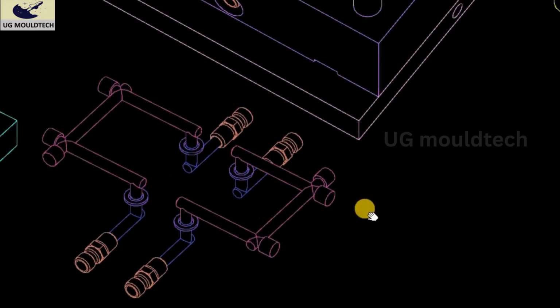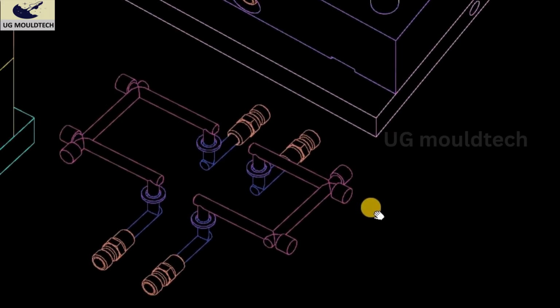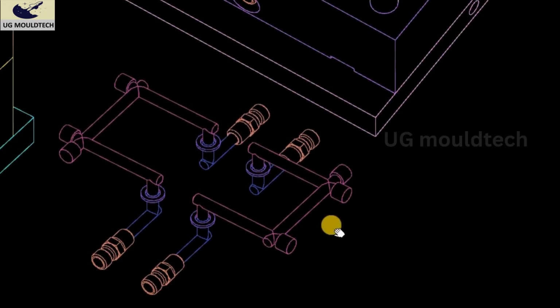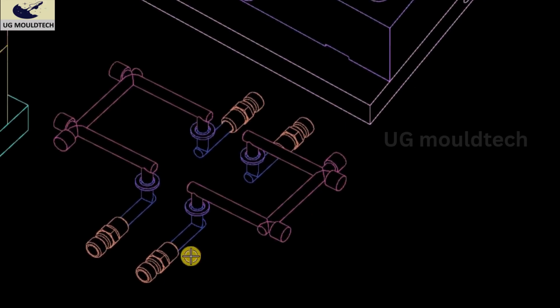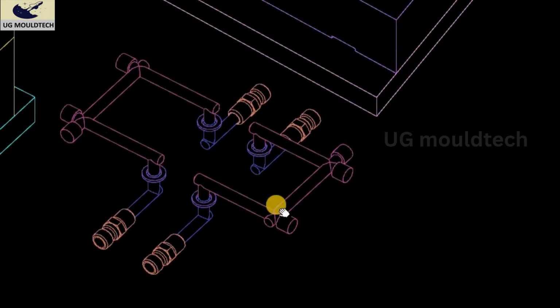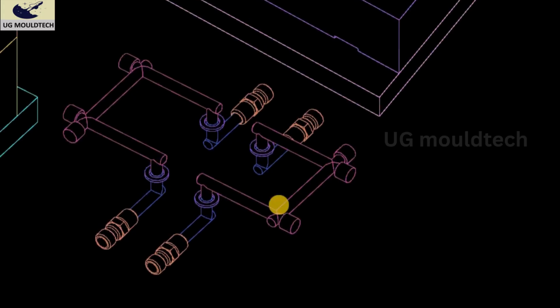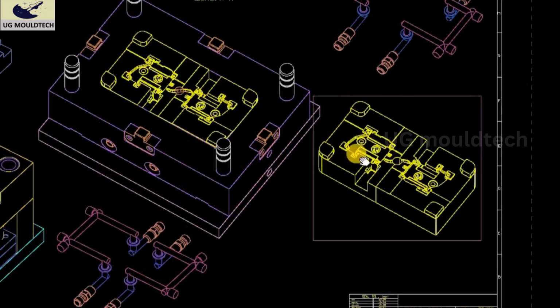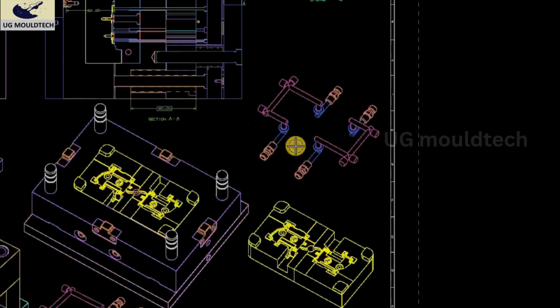The next point will be our cooling channel. Cooling is half the mold performance. Read the cooling schematic and plan review. Maybe C1, C2, this is the cooling channel. There are different types of cooling: straight drilling, baffle, bubbler, spiral, conformal, inserts. These are the different cooling systems.